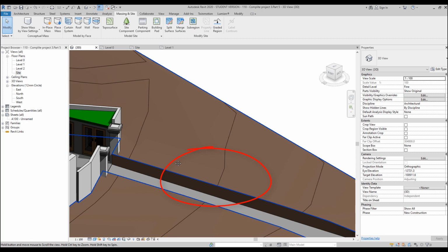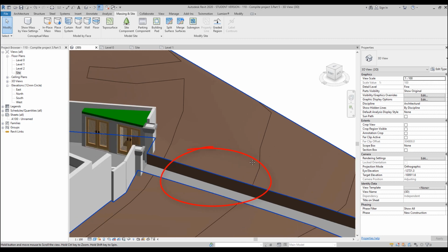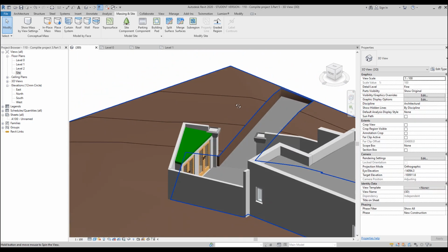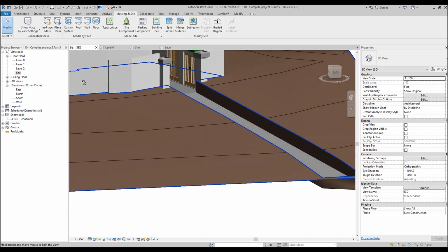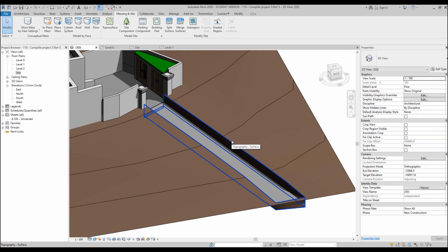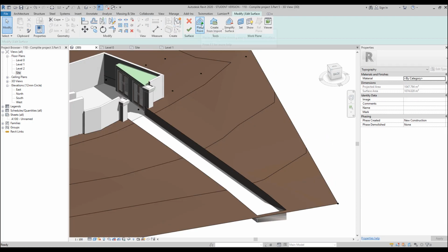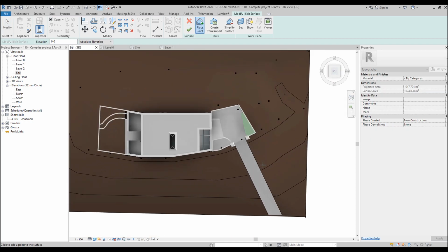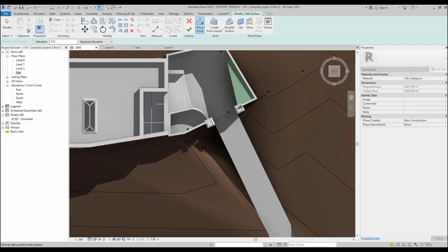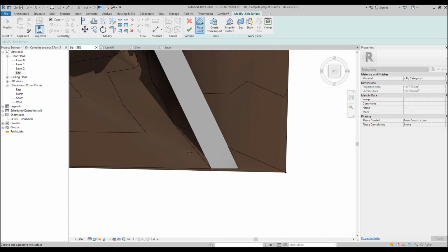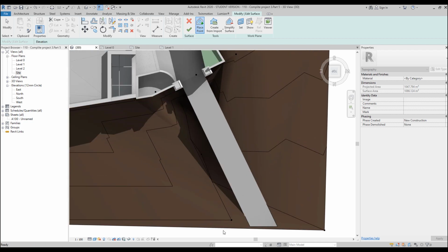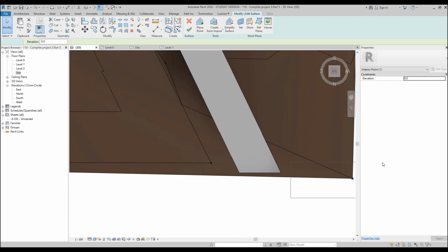Once you finish, you will see here are really big boundaries. I don't like it with the earth. So let's make some extra points around our future road entry. Now I will go to the topography. Again, I will use the points, and I will place points beside my road, just near it. We will manually set the elevation for each point to make it the same elevation as our road. Let's see.